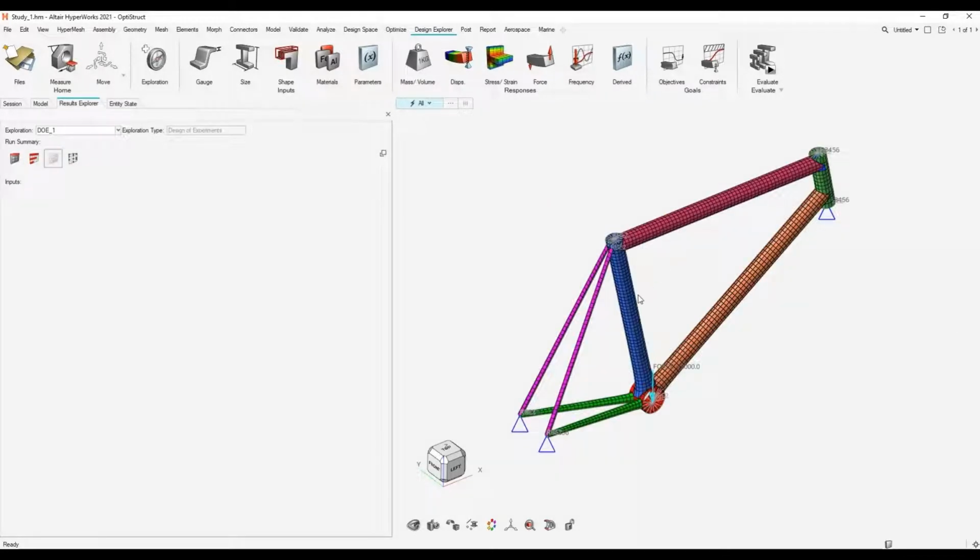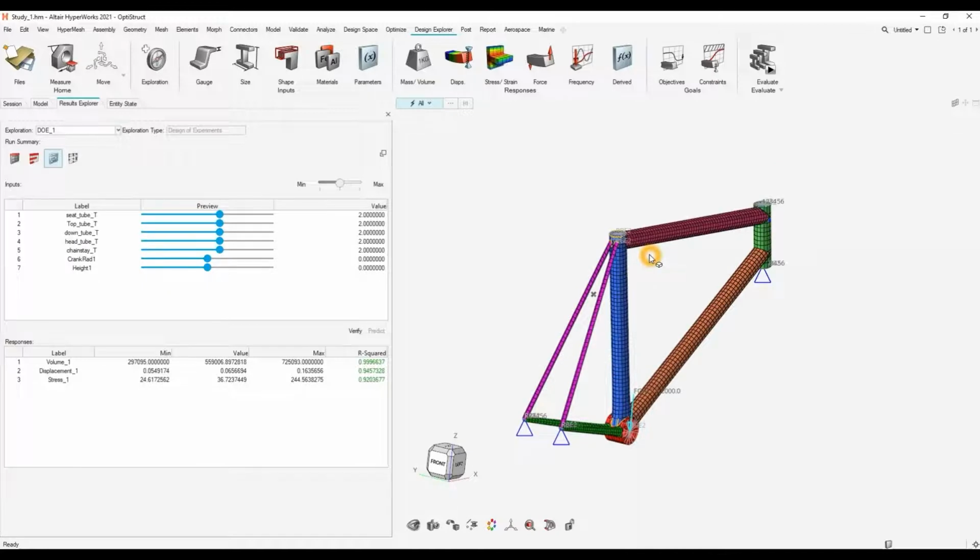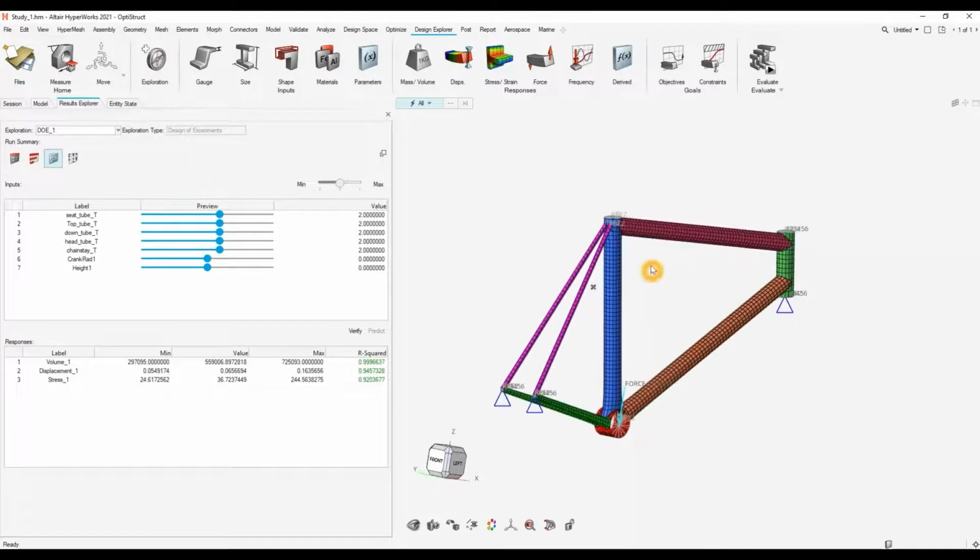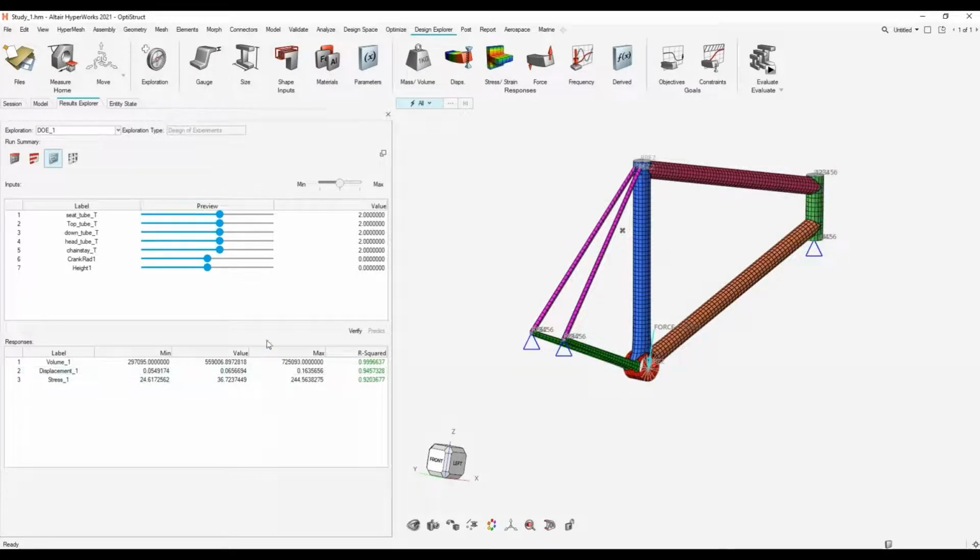So if we were to click on the trade-off button, what this is doing in the background is applying a surface fit to all of the data that you have. So where you see these different sliders, it will show you where you could slide to any different values, ones that you might not have actually solved for. So you can slide it to any values, and through the given data that you already have solved for, it will look at interpolating the results between them to get you the responses, so you don't need to go through and run another analysis solve all over again.